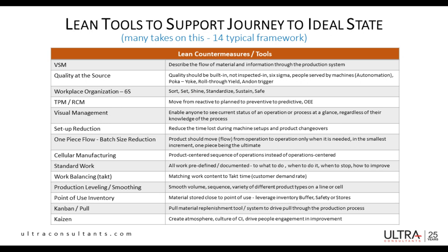Setup reduction, I already spoke to a setup reduction idea a minute ago, but this is where things like single-minute exchange of die technologies get taken into account, really to try and reduce interruption from setups and get to that flow, that perfect flow, that one-by-one flow, which is going through and can go on demand.